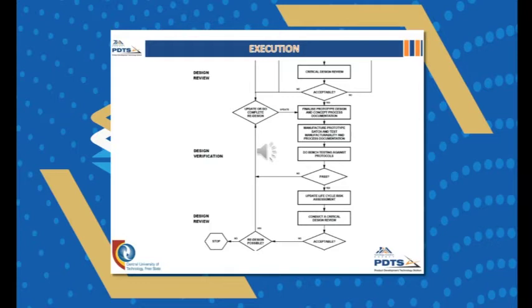Inspection and test instructions required for the first-off inspection, in-process, and final inspection, including testing, should be developed. Once all these aspects have been documented, the final prototype should be manufactured and the manufacturing equipment and manufacturing instructions will be evaluated. With the acceptance of design verification, a design review is done on manufacturing processes such as injection molding or sheet metal and tubing.